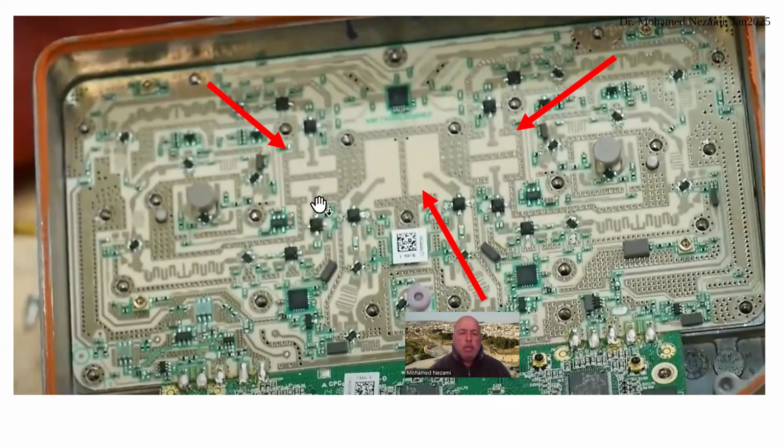And here's another one in here. You can see the vertical and horizontal probe, and you can see the probe is going right into the LNA, which is going to the hairpin bandpass filter and onto the rest of the down converter that way. An interesting thing to mention here, this one is 45 degrees slanted, and if you know why that is, please write me in the comments. I was looking at that and wondering, why did they do it that way? There's no reason not to do it the other way. I have no idea why they went with a 45-degree offset.